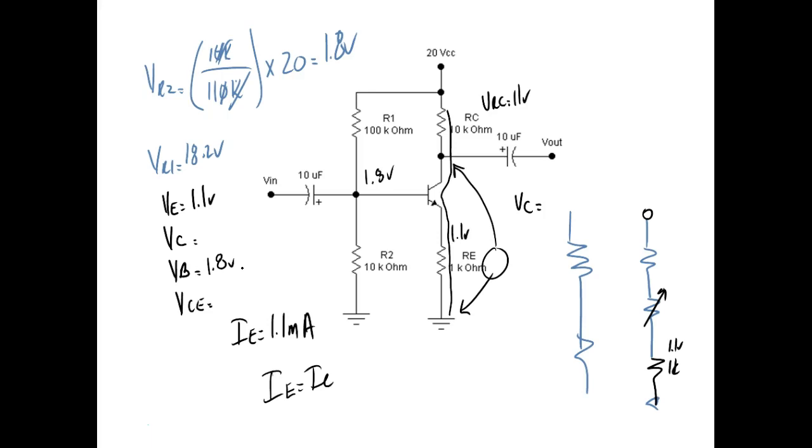So I've got 20 volts right here. This resistor drops 11 volts. I have 20 volts right here, and this resistor is dropping 11 volts. What's going to be right there? 9 volts. Whose law did we use there? Kirchhoff's law.